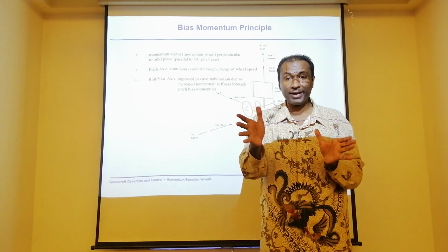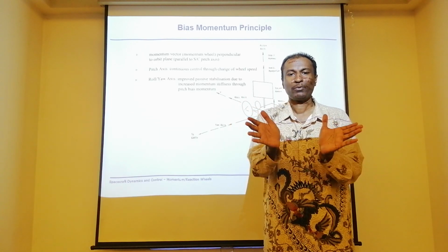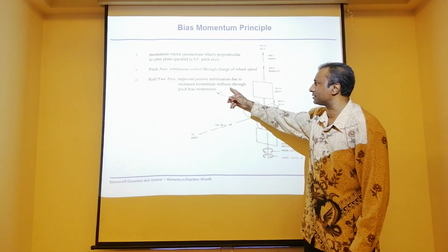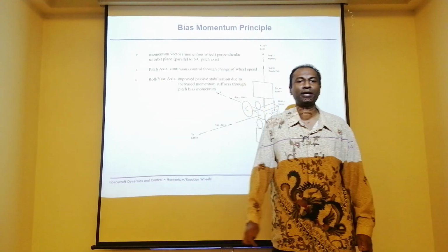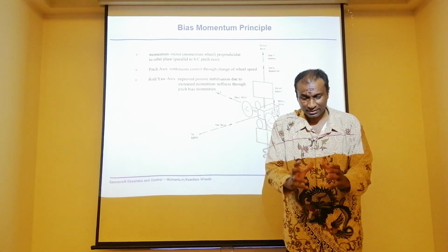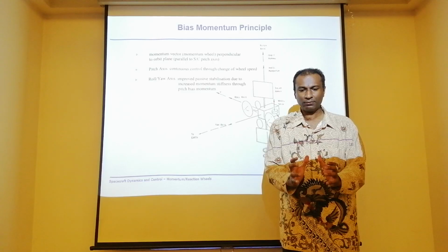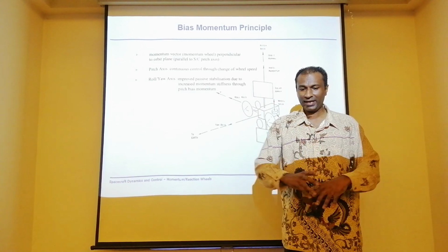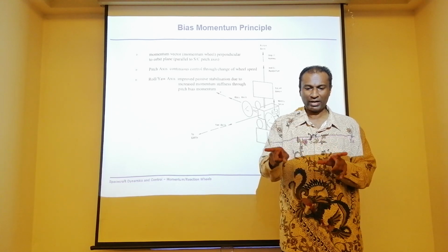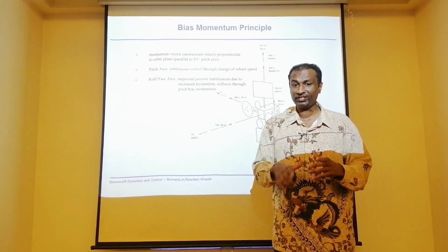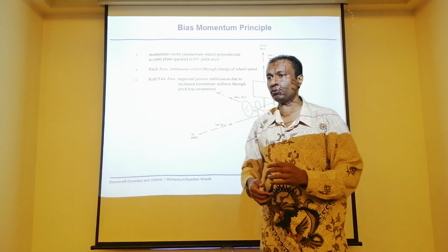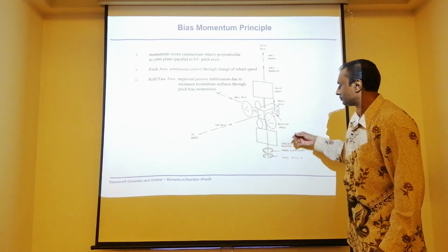The roll and the yaw axes are basically going to be quite stiff. So therefore it increases the stiffness of the roll and yaw axes by putting the momentum wheel in the pitch axis. Okay, it gives you stiffness to roll and yaw. But don't forget, for the pitch axis, it can produce active torque when you start speeding up the wheel. Okay, go on.